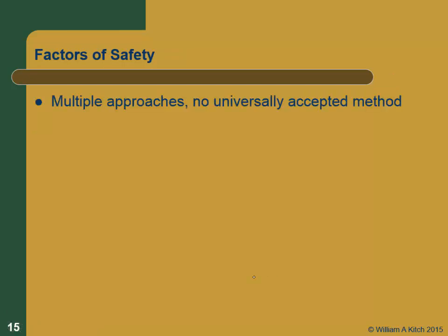So there are different approaches to ensuring an acceptable design, and as far as I know, there's no universally accepted approach. On the ASD side, there are two basic methods for doing this. I'll point out that this guidance comes from the 99 NHI, and the 2007 one gives you the geotechnical LRFD design methodology. As I said, if we have time, we'll spend some time looking at LRFD methods, but at the moment, I'm not prepared to do that.